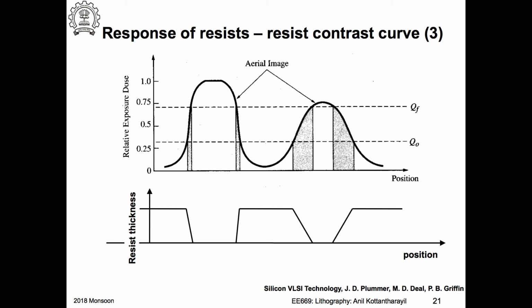They have different resist contrast curves, for example, so that when you develop, the bottom part is etched more than the top part. So you have something that goes under this. Okay, but for your line of sight deposition, this edge is the mask, right? If I have something like this, right, and I do the deposition, where will it get deposited? Here, right?